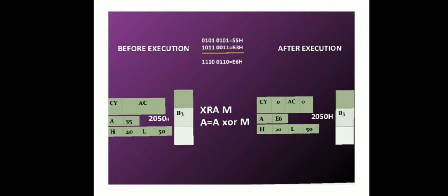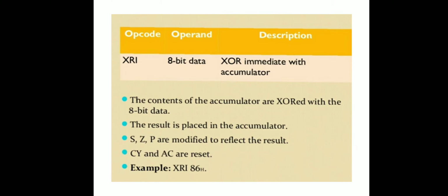Again, the XOR with memory. Then, after execution of this instruction, the result is stored in the accumulator, and the carry flag and auxiliary carry flag are reset. XOR immediate with accumulator.